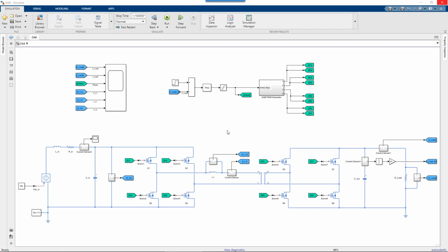This is really useful for this particular application of looking at solvers because that's actually a harder problem for solvers to deal with. You have to accurately capture the width of the duty cycle, and you have to actually capture the phase offset between the two cycles. So there's a lot of tricks that certain software might use under the hood that won't work in this case. So this is a harder one to see any optimization in, and it's good to show how those optimizations might break down the accuracy of a solver, and that will show up very clearly in this type of model. They're also popular right now a lot because of battery charging applications.